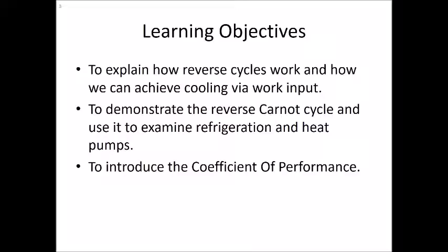We're going to look at the reverse Carnot cycle, and we'll see how we could take our understanding of the Carnot cycle and literally just run it backwards. So to turn work into heat, not heat into work. And we'll see how that relates to refrigeration processes. As usual, this will be highly idealized. So in subsequent lectures, we will then look at more realistic, more real systems.